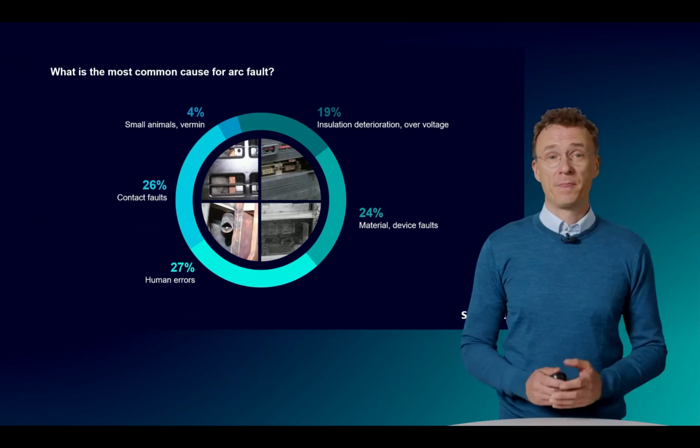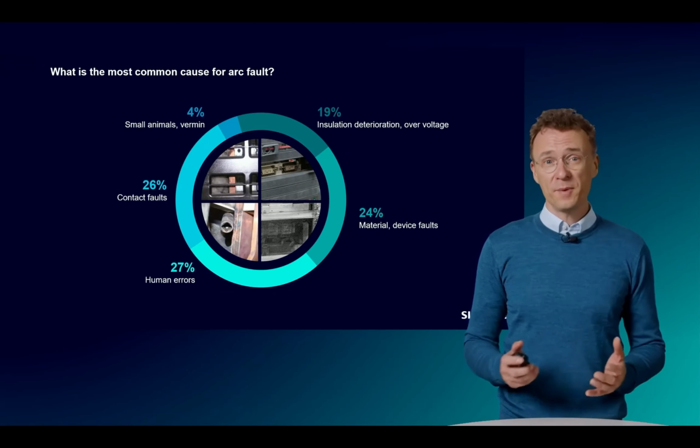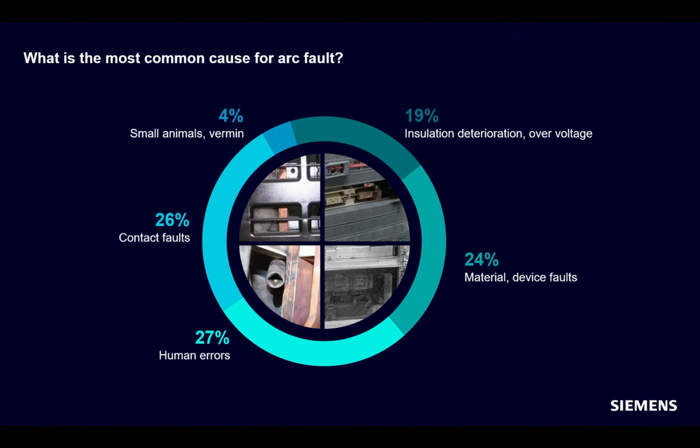The next one is, can the AQD be retrofitted in any type of low voltage boards of any make? We offer this system only as a solution for our Sivacon S8 switchboards. The next question is, what is the most common cause for arc fault? From the statistics, we can see that the common causes for arc faults are relatively evenly distributed. However, the most common cause is actually handling errors by the personnel.